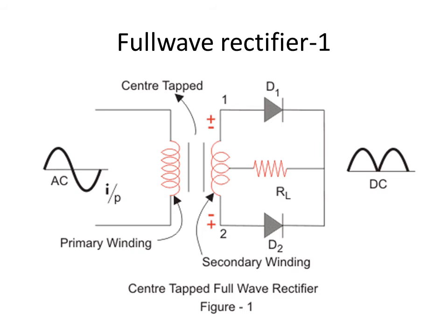One more thing I will tell you before we move to the next topic. I won't do the derivation here. For the case of full wave rectifier, you can proceed as before. In the case of half wave rectifier, you find out the ripple factor, which is root of IRMS square minus IDC square divided by IDC, and IRMS in the case of full wave rectifier is Im divided by root 2, and IDC you can evaluate.